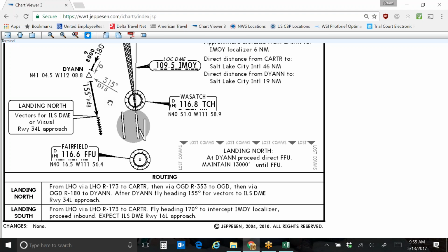So these systems are really cool. Let's say this other plane that was coming up the canyon also had TCAS. The cool thing about TCAS systems is that not only do they tell your plane what to do, but they also talk to each other in other planes. If it senses two planes getting too close to each other, those two TCAS systems will communicate with each other and give each crew corresponding instructions. If it tells one to turn right, it'll tell the other one to turn left. It coordinates with the other system so that it's not telling you both to turn right, or to turn into each other. They're really cool the way they work.